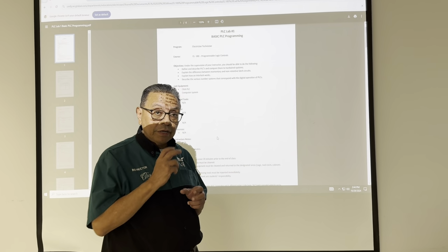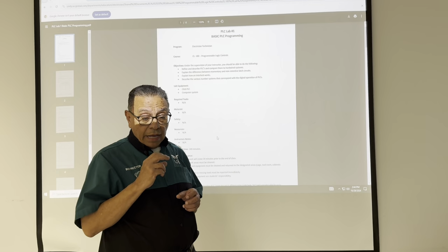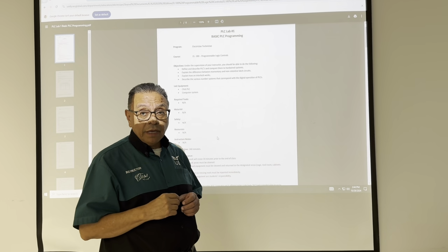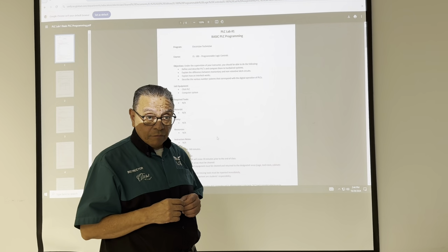So we need to connect an auxiliary contact in parallel with the green contact, okay? And this auxiliary contact is part of the contactor, any contactor for an electrical motor. It is normally open, but when we energize the contactor coil, even for seconds, this contact is closed, holding the connection. To stop, to de-energize the contactor coil, we press the push button, which is the red one.